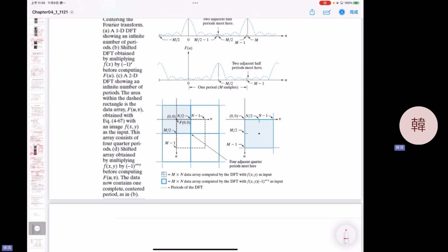This is the spatial domain, zero padding. I remind you, you have to do zero padding of your original signal. And what's the effect of this? When you pad zeros there, you get a ripple effect. Why? Because of the discontinuity.